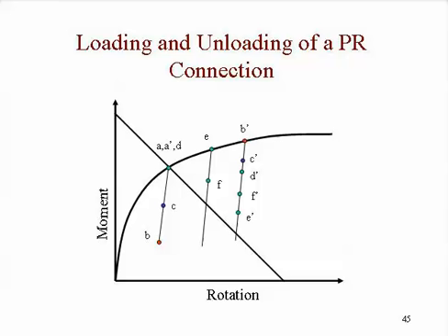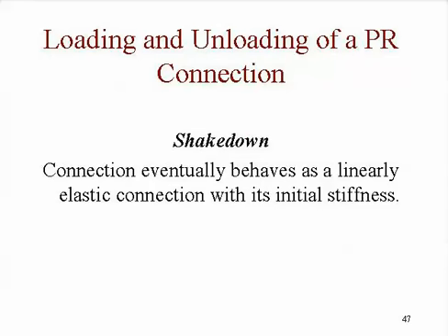Taking it off moves us up there. And if we keep going, and if we get beyond the point where the maximum lateral load that this system is ever going to feel, the system has gone through what is called shakedown. And in that situation, the connection is behaving linearly. Once it's gone through all of that permanent deformation, the connection behaves linearly.